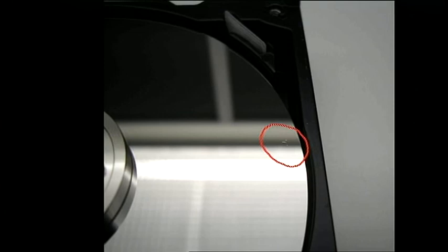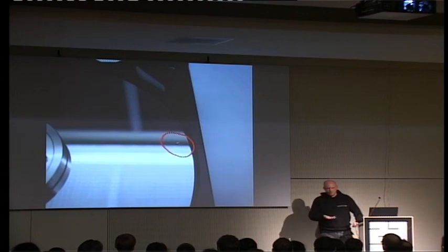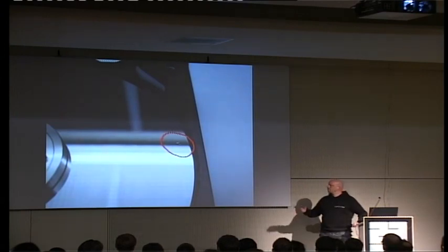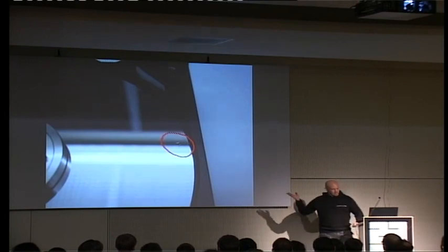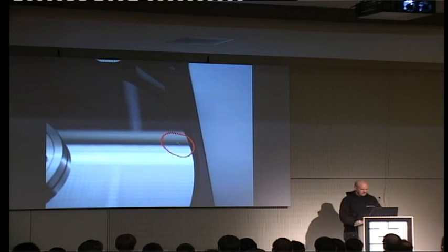Yeah, it's a nice mark. It looks like a little man with a nose, but it's not. In fact, it's where the heads were. This is actually a dropped hard drive, and that's what we call spots. It's when you drop the hard drive and the heads in their springs go up and down, and they knock on the surface. Then they leave sort of grooves in the surface, which will in turn destroy the next head you will try to fly over the surface, unless you take special measures. Anyway,